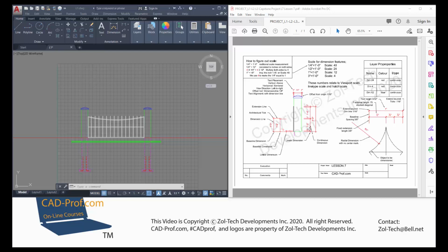And we have to zoom in at a certain factor on our window to represent that scale. And that's what these numbers represent here. So I've done a very quick summary of some of the more common unit measurements we're going to be using in this exercise. I've also shown how to calculate this, and it has to do with changing how we typically look at our scale, 1/4 inch equals 1 foot, to a ratio, and the ratio always has to end up in a 1 to something.